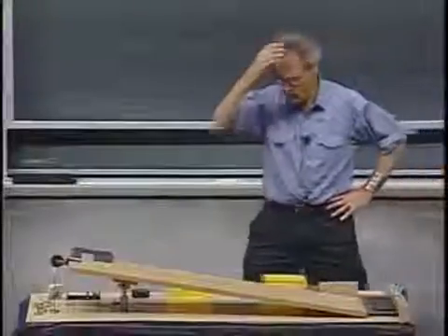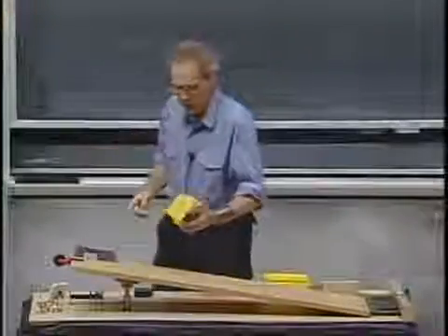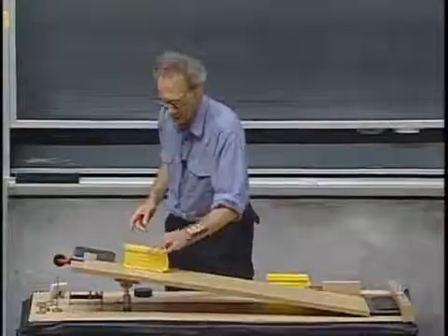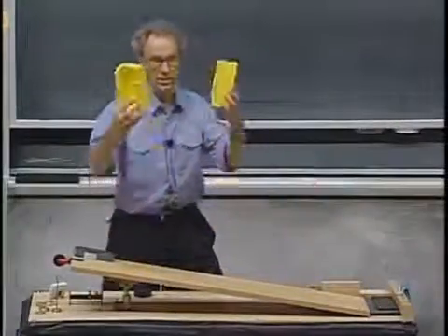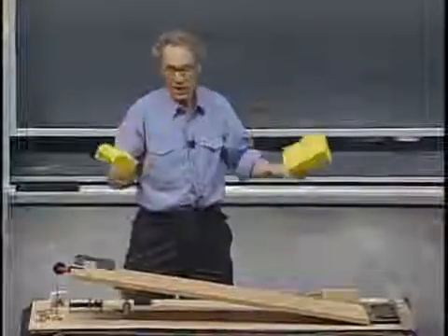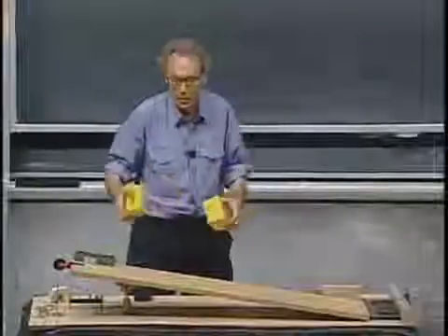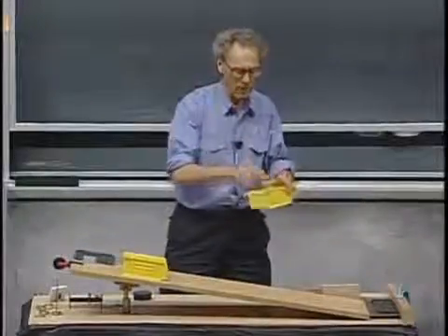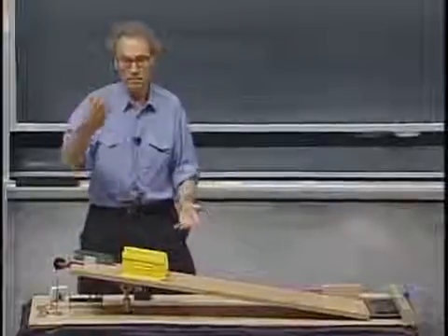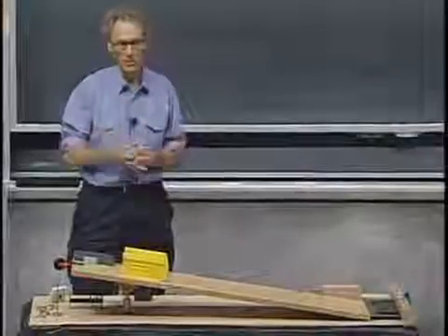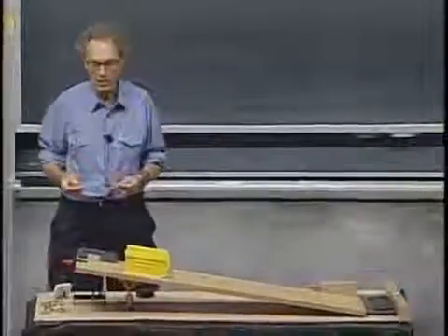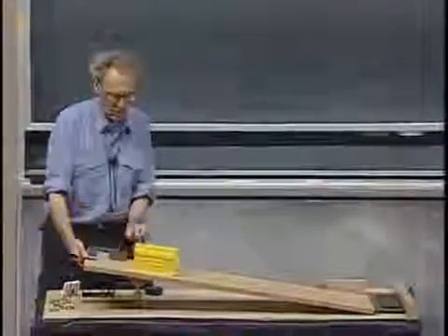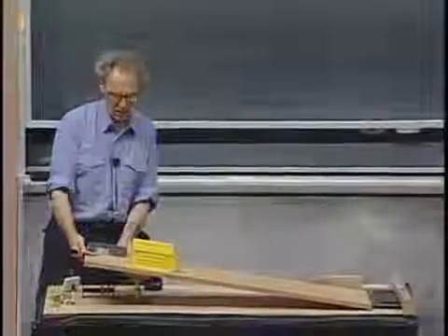I told you that the friction coefficient is independent of the mass of the object. I have two identical bins here. Well, as far as they can be identical. Maybe one at the bottom is a little rougher than the other. But in one, I'm going to put 200 grams, which is about 5 times the weight of the bin. And then, when I tilt them, they will go at the same angle, because it's independent of the mass. So let's try that again, and see how close they are.